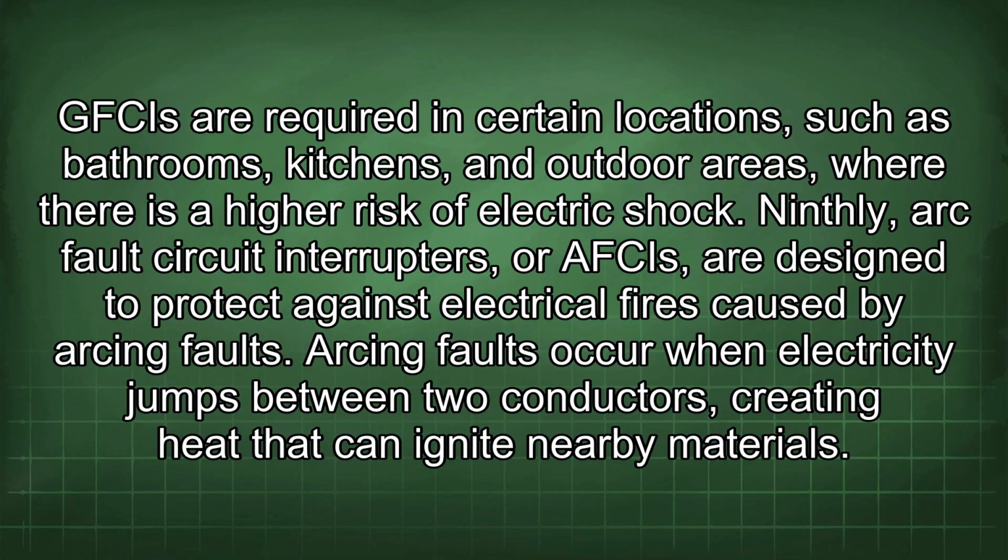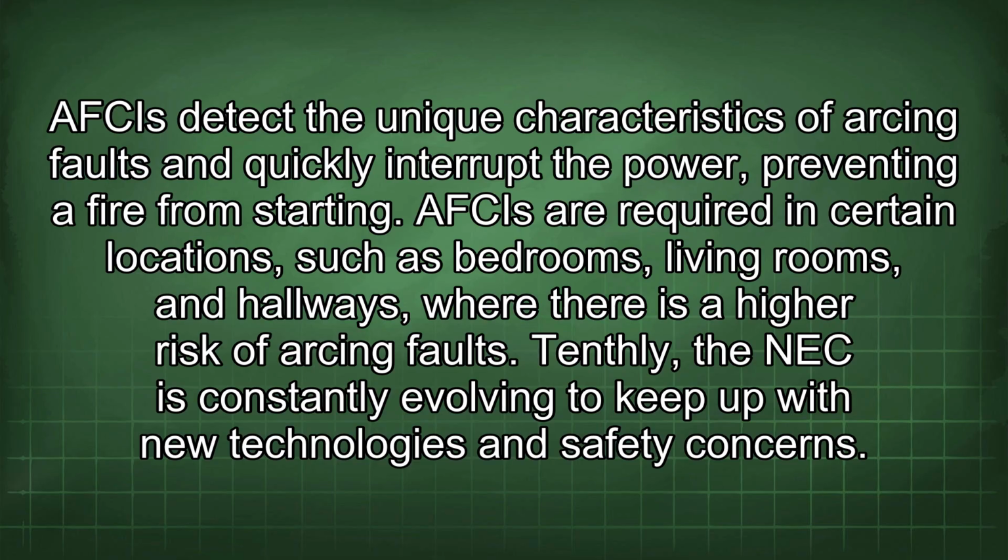risk of electric shock. Ninthly, arc fault circuit interrupters, or AFCIs, are designed to protect against electrical fires caused by arcing faults. Arcing faults occur when electricity jumps between two conductors, creating heat that can ignite nearby materials. AFCIs detect the unique characteristics of arcing faults and quickly interrupt the power, preventing a fire from starting. AFCIs are required in certain locations, such as bedrooms, living rooms, and hallways, where there is a higher risk of arcing faults.